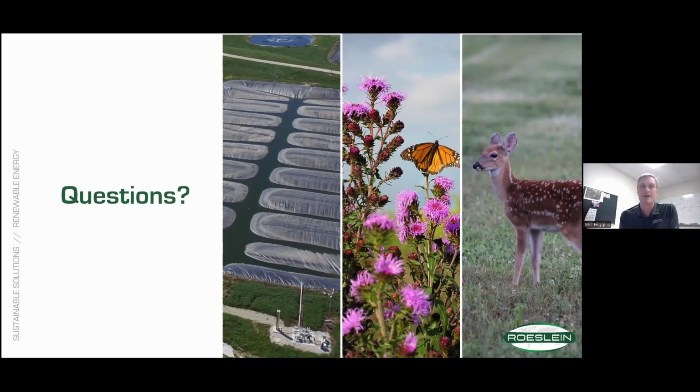And a lot of times these are very rural and remote areas, so the utility systems aren't designed to handle that high of an electric load. And so you have to make some of those decisions. That's one of the things that happened to us in Texas when we did the amine system. The local electric system couldn't handle the compressors that we were first, I guess, proposing. So that's one of the reasons we went to an amine system, because they use a lot less electrical, but they use natural gas to regenerate the amine.